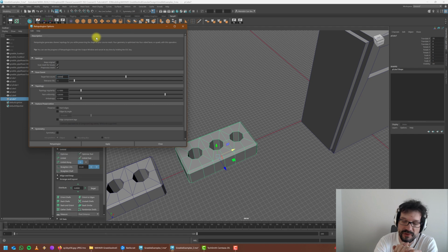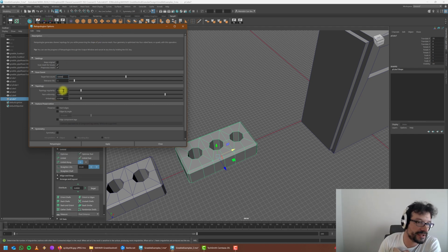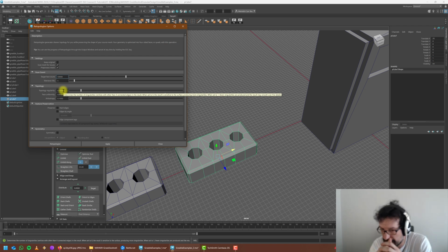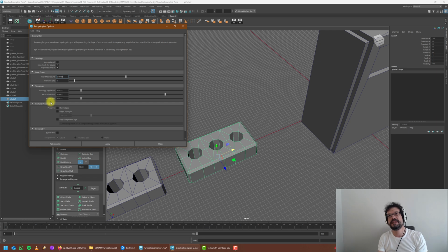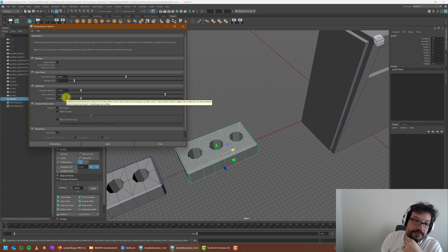Okay, now let's remember the retopology standards. Like regularity, for example, they come with their explanations. So regularity concerns how many quad faces we are using. The more irregular the object, the more singularities will start to happen, like the pinching areas, vertices with more than 4 connections. Okay, face uniformity, in this case, the overall differences between the sizes of faces, meaning that small quads and large quads will happen when the uniformity is low. Okay, and anisotropy is the rectangularity of the faces. The less anisotropic the setting is, the less anisotropic the face is. It will start to turn into a square, basically.